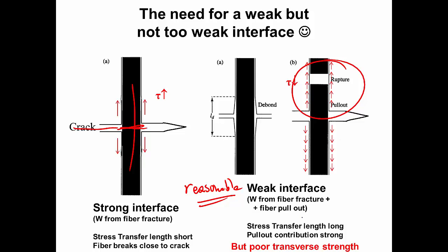The only problem is that the presence of such an interface also provides a path for things like oxygen and allows for interfacial reactions that essentially with time negate the contribution of such an optimized interface to the fracture toughness of the material. And of course, the transverse direction has a fracture toughness that is quite reduced.